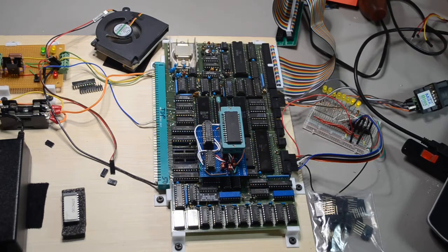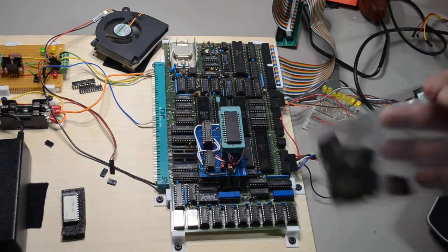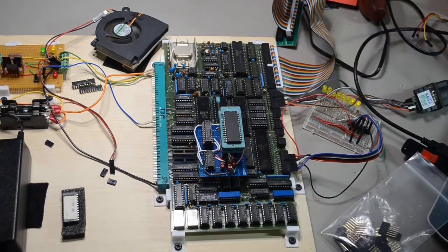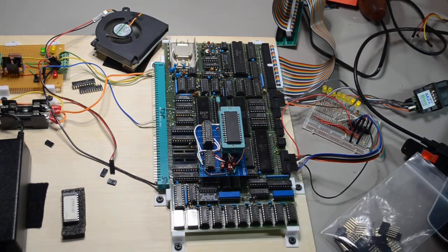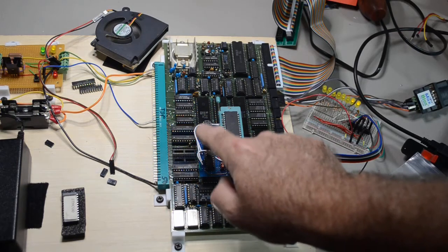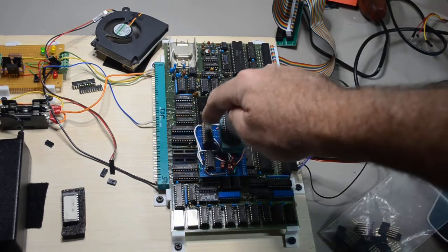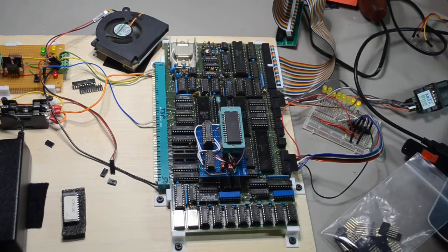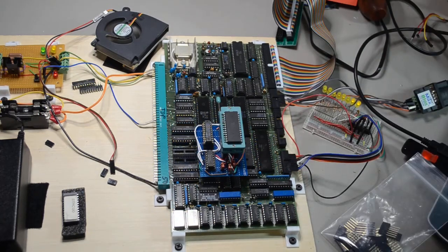So, one way I fixed that problem was just put my ZIF socket, which has header pins soldered onto the bottom of it, into the top headers there. So that was an easy problem fixed. And then I found another set of headers that the IC chips would fit in, and I stuck them in here on either side of the PAL chip. So that raised that PAL chip way up, but at least it's making good connection now. So everything works as far as it works with the limitations of the board now, just with those mistakes.